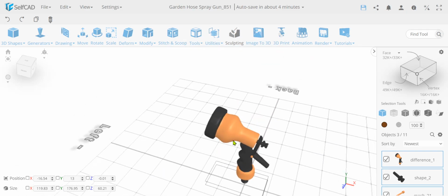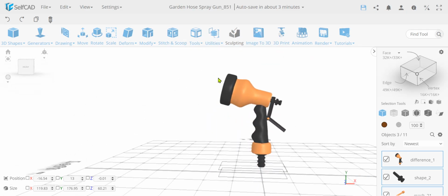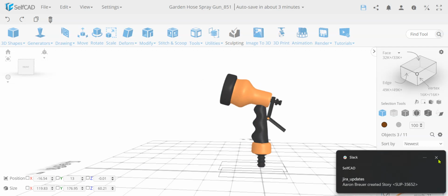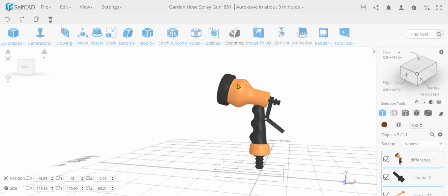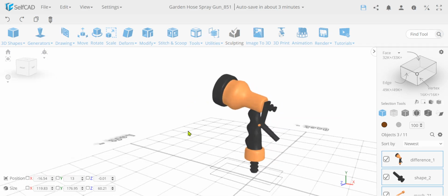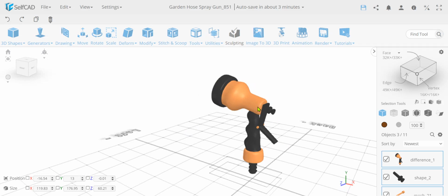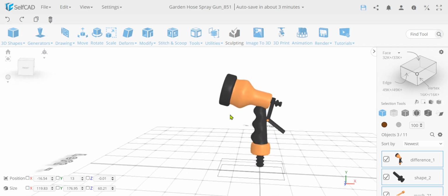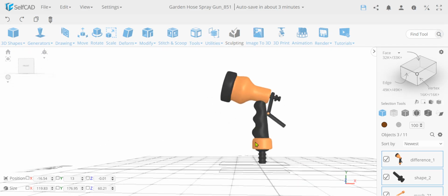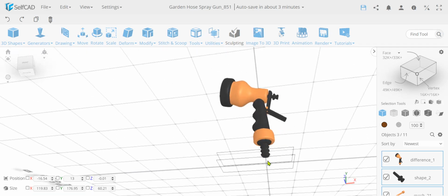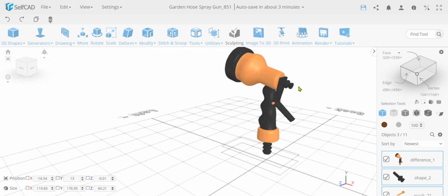So just to recap what we have done, we have created some basic shapes over here, just to get a visual look of how the profiles need to be created. We then used these shapes to copy the profiles instead of drawing the profiles. We then converted the profiles into splines, because if they are rounded they need to be splines for loft. We lofted them. Then we did the same thing in the bottom, same flow, but we also added guides to make this rounded piece. And then we used shape generator to create this piece plus this piece over here.